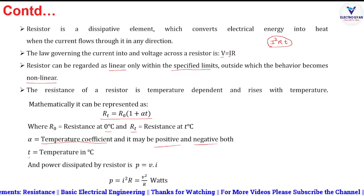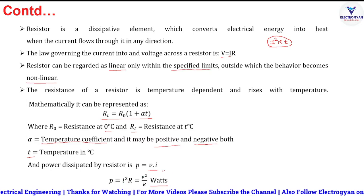T is the temperature in degrees centigrade, and the power dissipated by a resistor is P equals V into I, if we are expressing in terms of voltage and current, and P equals I squared R or V squared upon R watts. This is the power dissipated, and I squared RT is the heat produced. So this is the brief introduction about resistance.